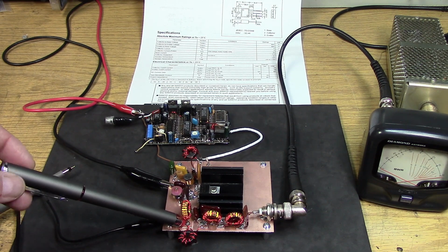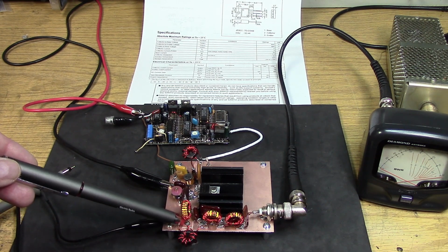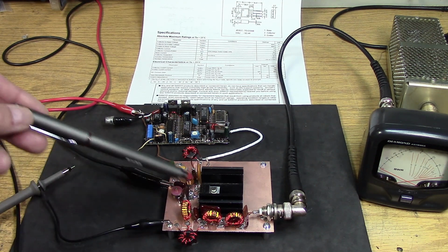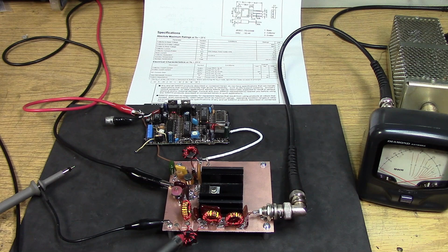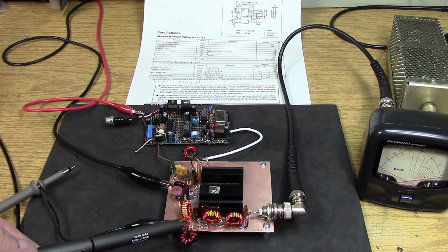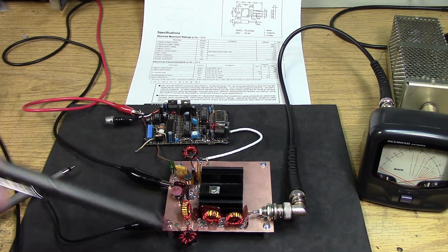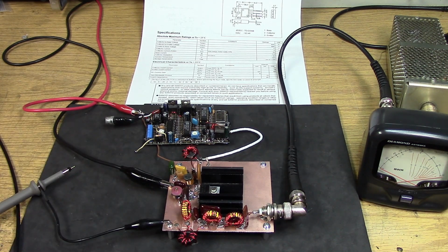This thing was asking for something like 10 ohms at this point to make it go into Class E properly. So I have another one of those 1-to-4s, this time the other way. It goes from low to high, hopefully bringing me back up to 50 ohms here. And this network is just simply the harmonic filter. So I hope you all caught that. Looks like a lot of parts, but let's see what happens when we turn this thing on.